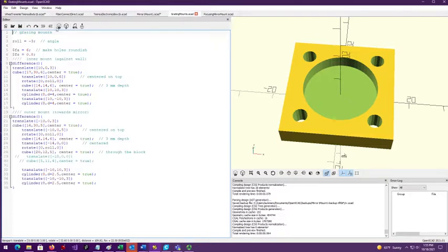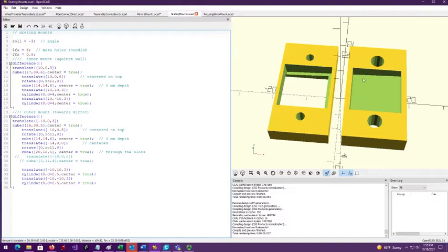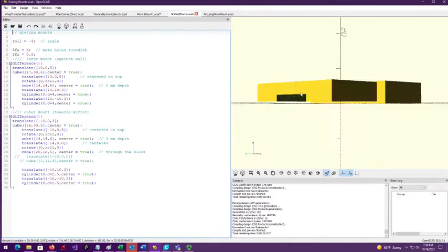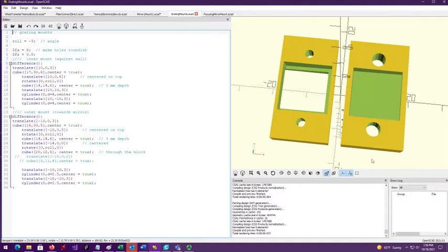All right, let's see. Grating mounts. You have to have a grating, and this is the inner grating mount, and here is the outer grating mount, right? The inner grating mount and the outer grating mount. These are for 13 millimeter square ruled diffraction gratings that you can buy from any optic store. And the plan here is you drop the grating down in this one, you drop this one on top, you turn it over. These little areas here will hold it in place, and you screw this whole thing to the spectrometer body.